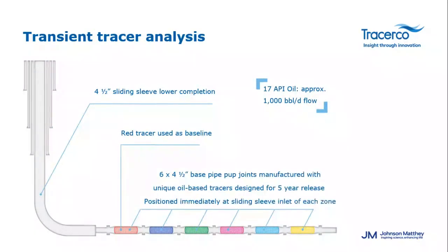I mentioned the use of a transient study in order to capitalize on the opportunity to quantify zonal production. In order to do this, the production pipe length, tracer locations, dimensions, and expected produced volumes need to be known. Volumes and the production system design can affect the tracer pulse's arrival timing at the sample location, requiring changes to the schedules. Sampling must be done during the correct timing to capture the breakthrough, peak, and mode.